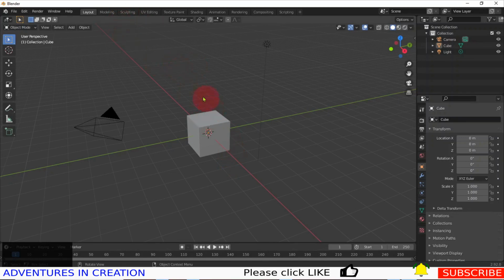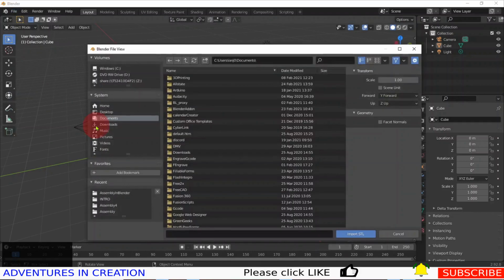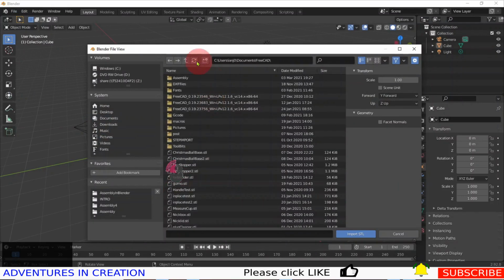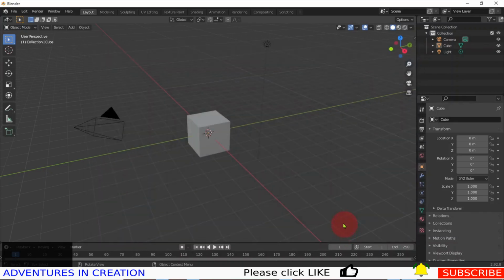So first thing I want to do is bring in my main body. So I'm going to say File, Import, STL. Then I need to navigate to where I saved those STLs. I saved them in here under Assembly. So the main body, I'm going to import it.